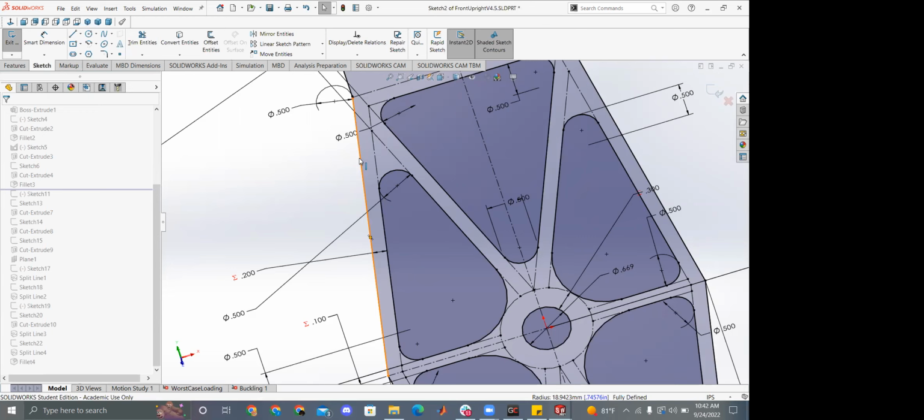I've done it before. I've drawn out a pocketing arrangement. Oh, this is gonna be bad. Bear with me. Sorry, Rishi, I know this isn't being recorded. But I've done something like this where it's like, okay, this looks like a fine pocketing arrangement, and then I go to the model and I put fillets on it, it fills in that part, fills in that part, fills in that part, fills in pretty much the entire block. So sometimes if you have a lot and there's small angles involved, you want to check it with a sketch fillet. You might not want to actually use a sketch fillet.